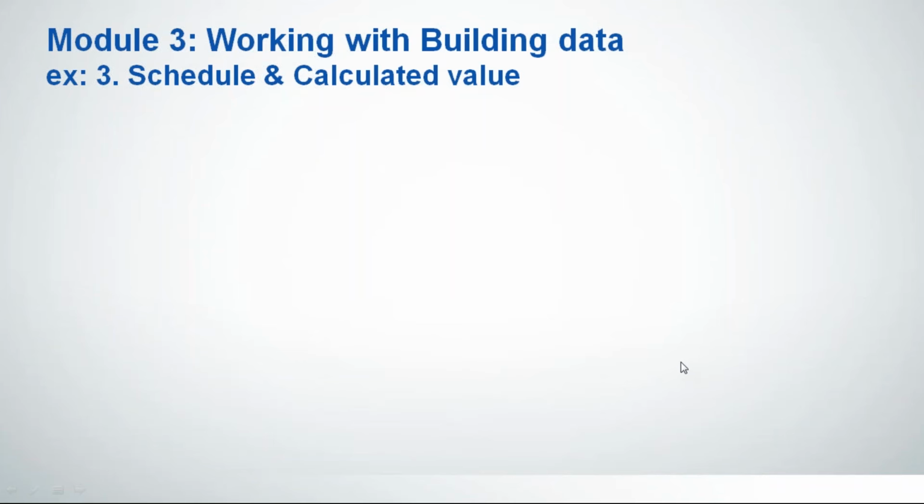The same application can be used for schedules and calculated values also, because every time we calculate our brick counts or bill of quantities, which will be in our schedule, it is not available as a parameter in our model. So with the same logic, you can transfer the value from one place to another place.